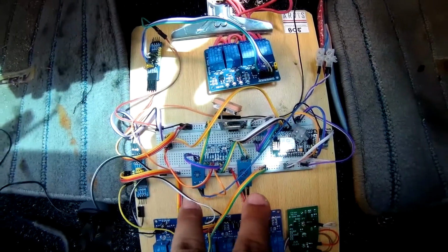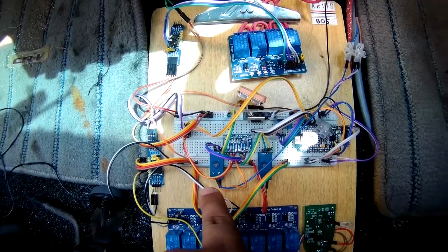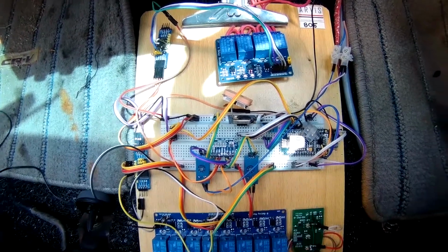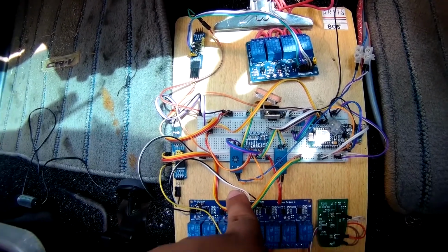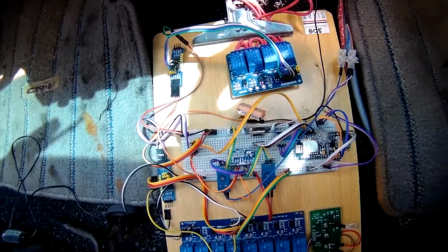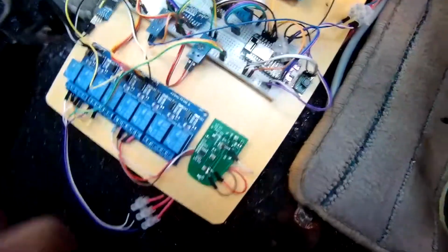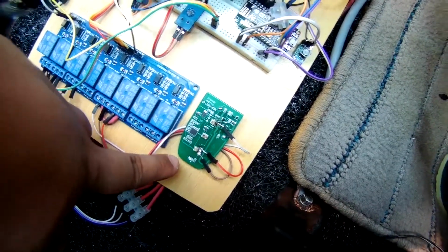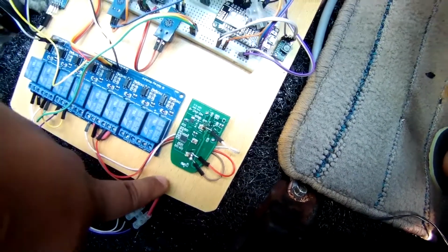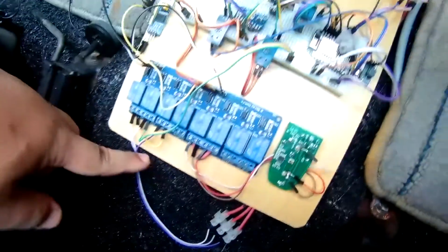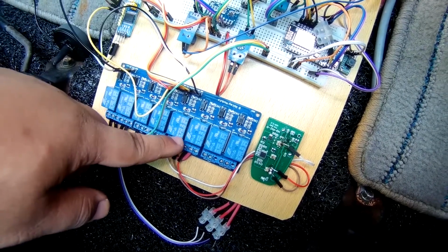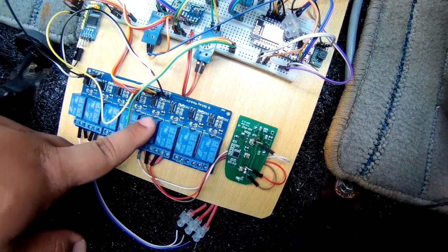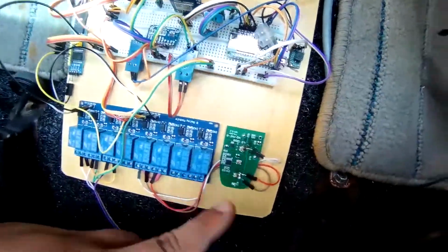Okay, the two modules here are the voltage sensors, because I need to sense the voltage of the battery and also the voltage of the car signal, because the car signal will trigger the alarm status of the car. Okay, here this thing is the original remote car alarm. I attached the cable to this relay, and this relay will act as the button. It's like we touch them with the fingers, but the relay does it.